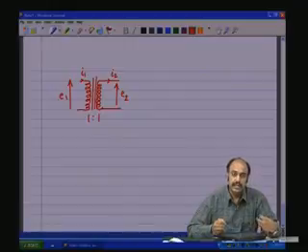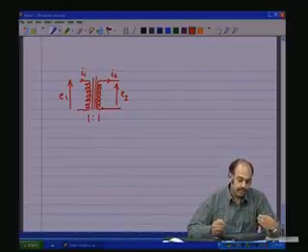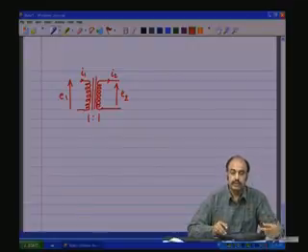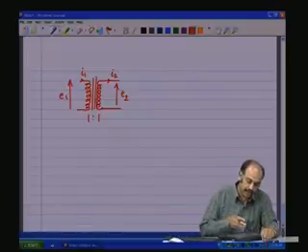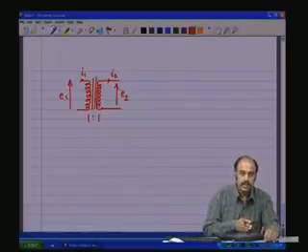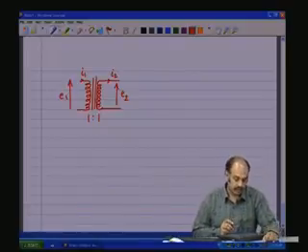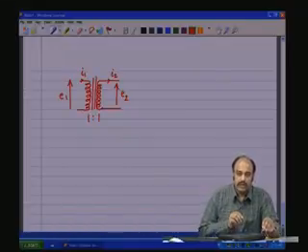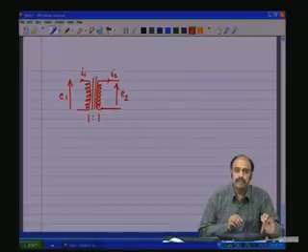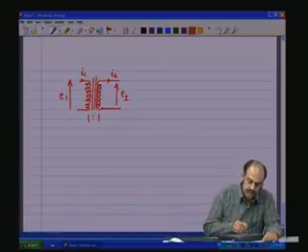The main function here is that galvanically the primary portion of the circuit and the secondary portion of the circuit are isolated, meaning there is absolutely no contact between the primary portion and the secondary portion of the circuit. For applications where one uses a transformer just for the purpose of galvanic isolation between one part of the circuit and another part, such a transformer is called an isolation transformer.